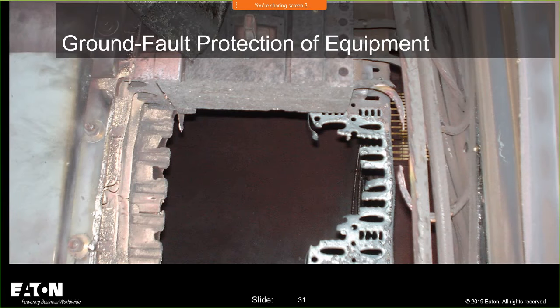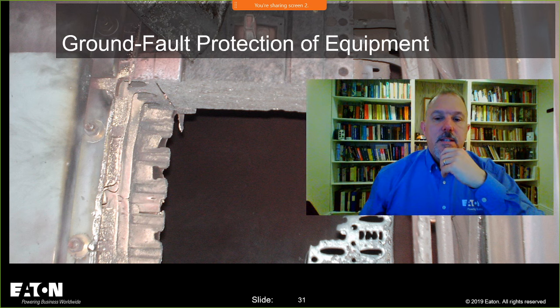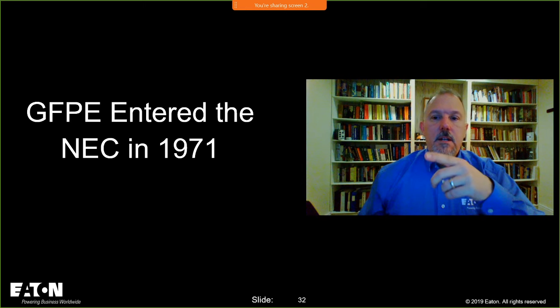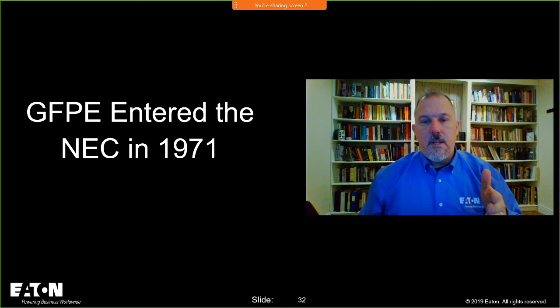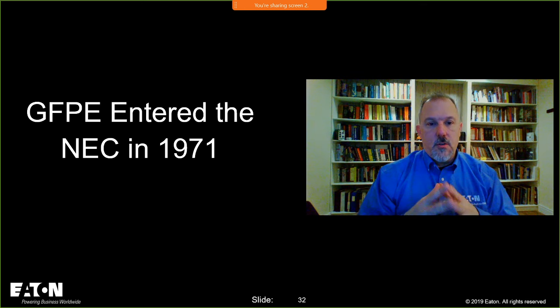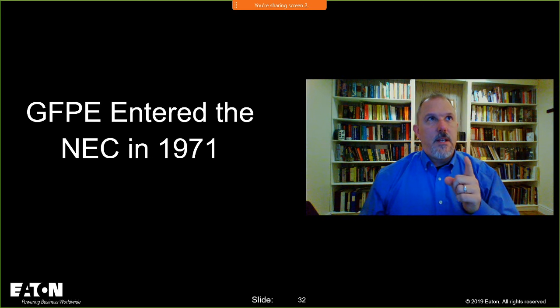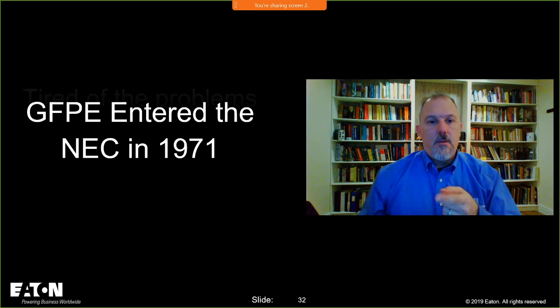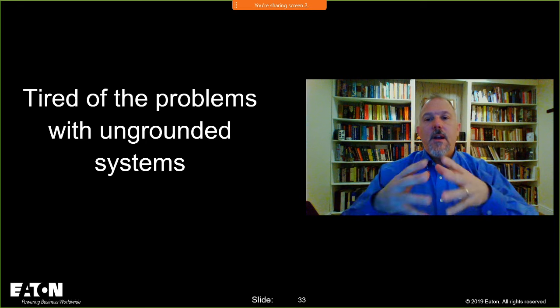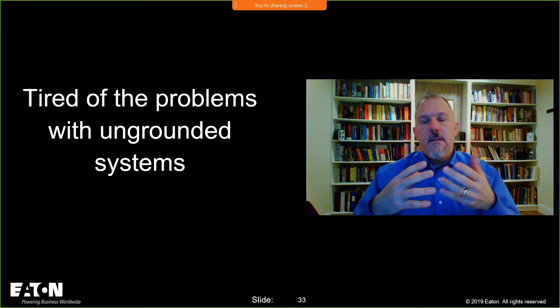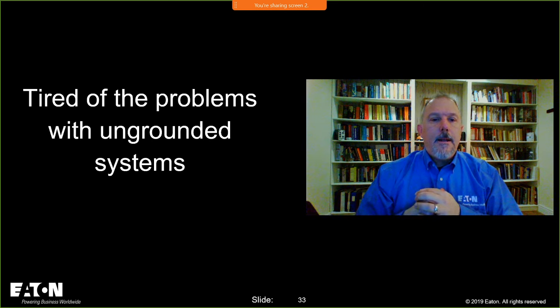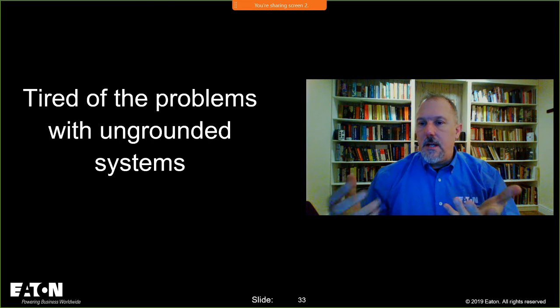So I want to just real quickly walk through this topic of ground fault protection of equipment, because I think it's a good discussion to understand some of the history there. GFPE entered the National Electrical Code in 1971, and that was for service entrance equipment. It's interesting to understand why it went into the code and what its function is. They were having problems in the 50s, 60s, and into the 70s with arc flash events and burn downs of service entrance equipment.